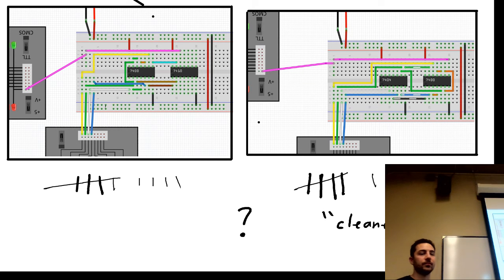Where is the banded wire, is that part of the wire color selection? It's right next to it. So there's a drop down, and next to it there's a checkbox for banded wire. It says banded. You click on it. The only sort of cheap trick I pulled here: if you make a white wire banded, it still looks like a white wire, white banded with white. So I actually made this a black wire and then banded it. I could have switched the colors around, but that's what I did.